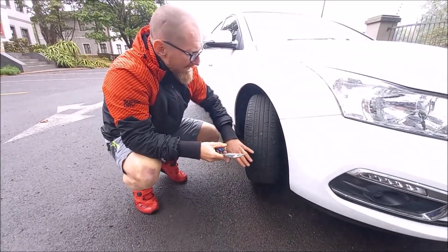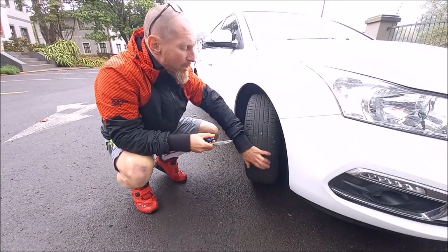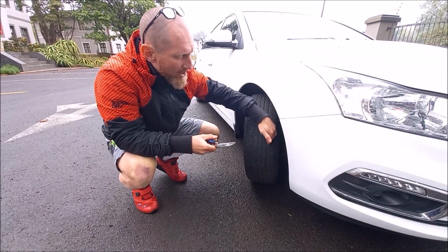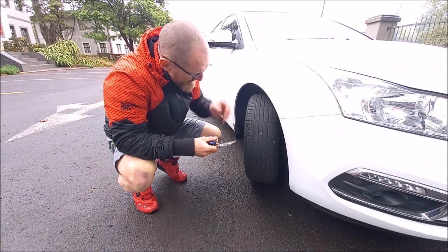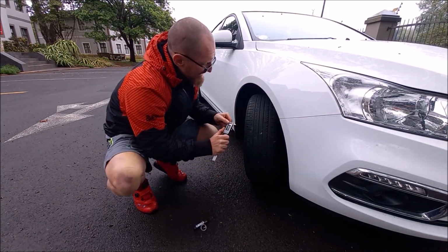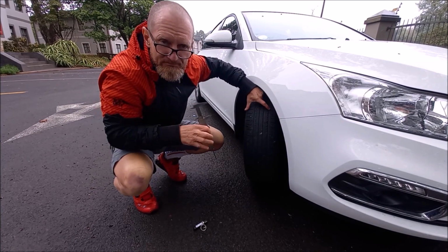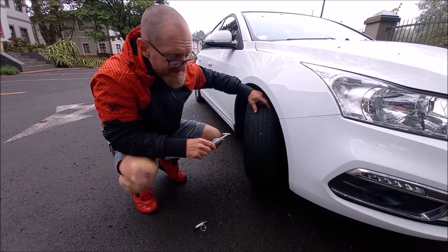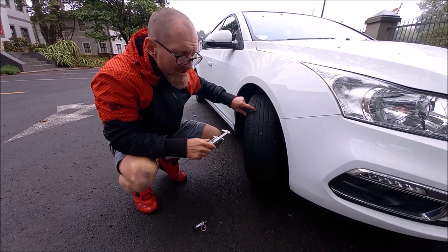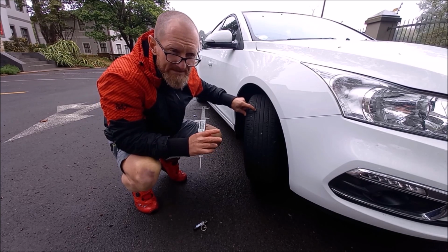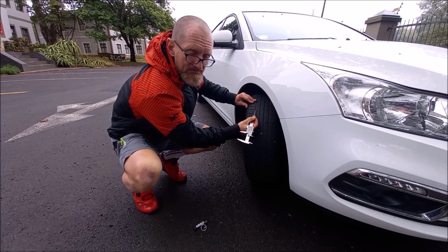Very, very important. In any crash investigation, one of the most important things is the tires, especially when there's wet weather involved. The dispersion of water from under the tire is reliant totally on the channels, which are the main channels that we see here. In each one of these channels, they have what is called a TWI, tread wear depth indicator, which is the little nipple that fits in between each one of these channels. That little nipple is the minimum required height by the OEM, by the manufacturer of this tire. Once your tire reaches that little tread wear depth indicator, the tire is then illegal. The fallback within the National Road Traffic Act is 1 millimeter if the tire does not have the tread wear depth indicator. If there is a tread wear depth indicator, that is your minimum requirement.